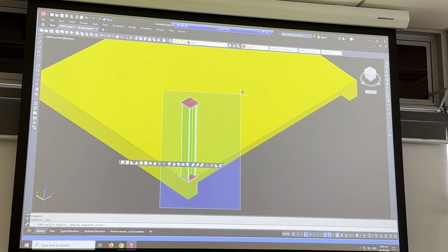So, just a warning, when you do a window copy like that, you don't know what's over here, and especially when you start turning it around, you end up with your main drawing in the background, and you start moving it, and then you go back to your main drawing and go, someone's ruined my main drawing. So yeah, the other thing is try and do lots of saves, because it's like a time bomb, this one, believe me. At some point you're probably going to have a crash.